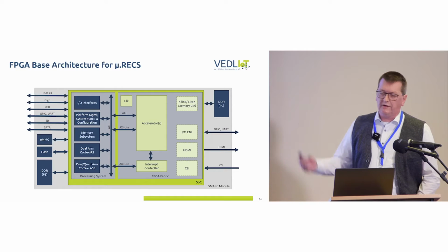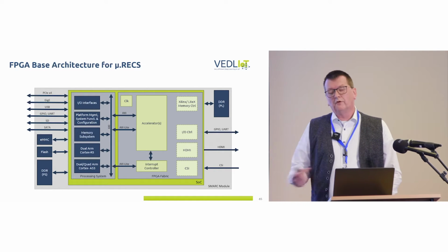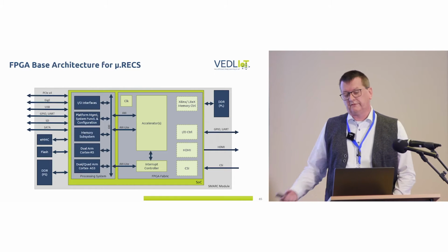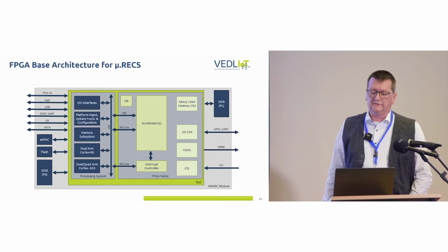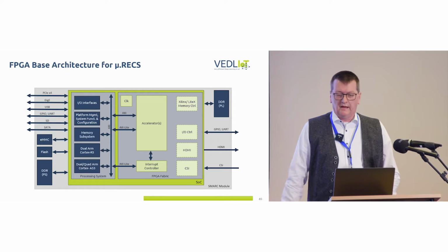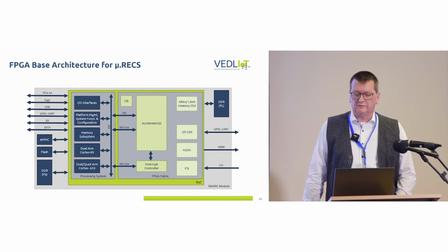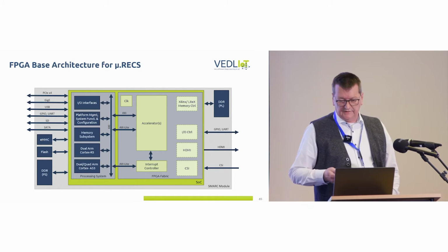Nothing surprising here. We have the processing system. In the UltraScale architecture, most of the interfaces are directly provided by the processing system. We have the accelerator, in the easiest case simply one big accelerator on the FPGA, and then there are additional I/O units, additional interfaces, which can be implemented in the programmable logic in the FPGA fabric.